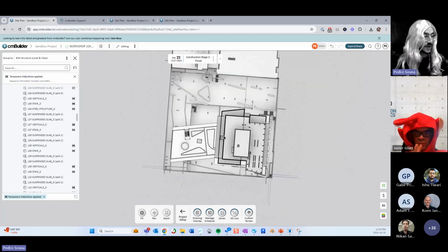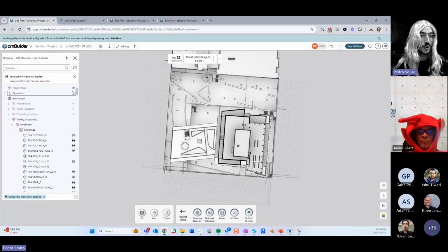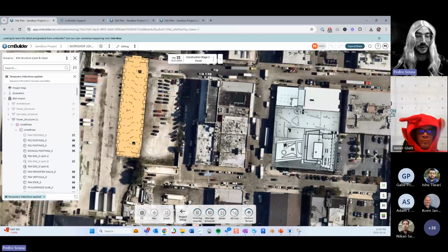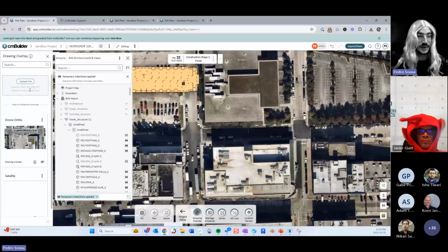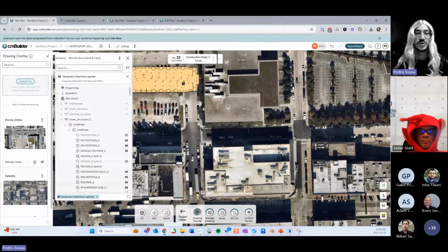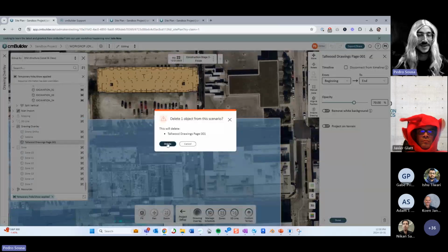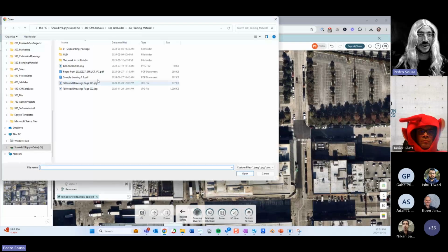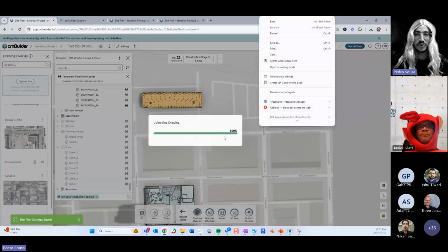Grid lines, depending on where they're coming from: if you can import a 3D geometry that shows those grid lines as a plane, you can snap to it. But if you were working with a drawing only, you could create those grid lines as a template, right? So let's say I'm going to import a drawing somewhere on this view. I don't have a drawing prepared over here, so I'm just going to find something that should work. That was a bad example because that drawing doesn't have grid lines. So let me find a drawing with grid lines. This one does. And I can place this drawing somewhere.